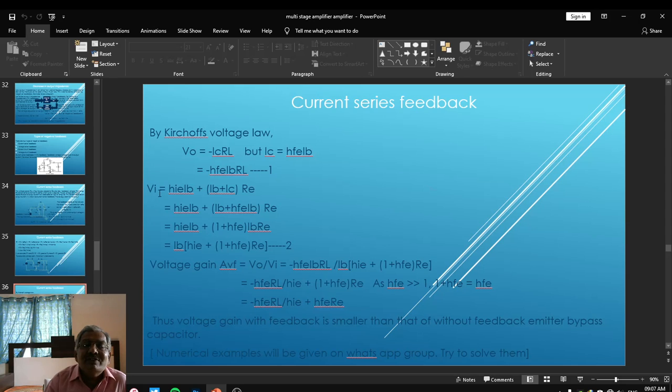Now the input voltage VI becomes equal to IB HIE plus IE RE, and IE is equal to IB plus IC. Directly I have written it. But IC is equal to HFE IB, which we have considered here. Put it again in the equation so that VI is equal to IB HIE plus IB plus HFE IB into RE.